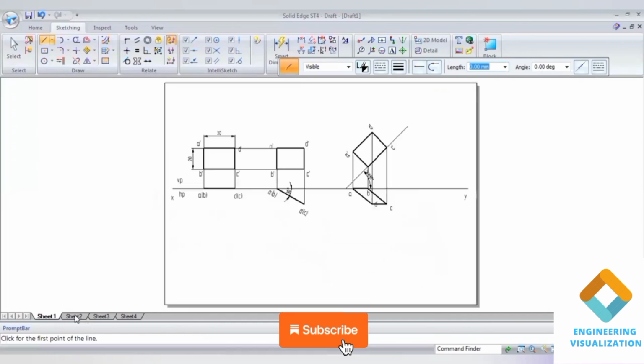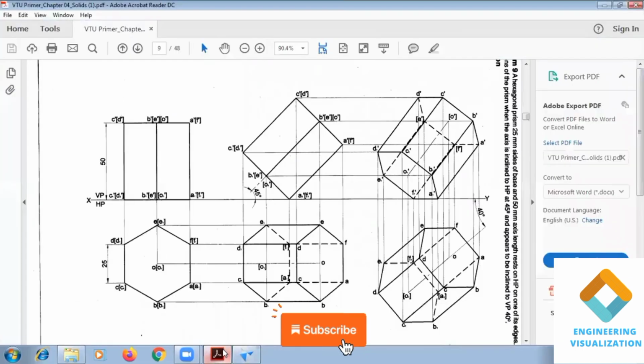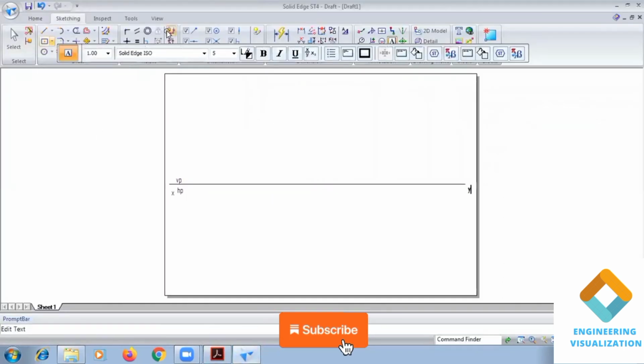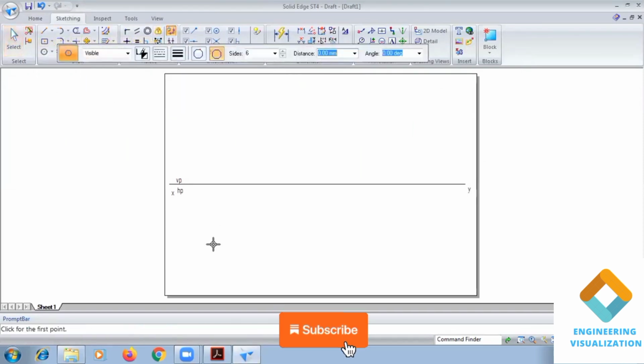Problem number 6, with respect to the edge here. A hexagon of dimension 25. Make sure the maintain relationship icon is on. Then use polygon by center, 6 sides, with respect to edge.